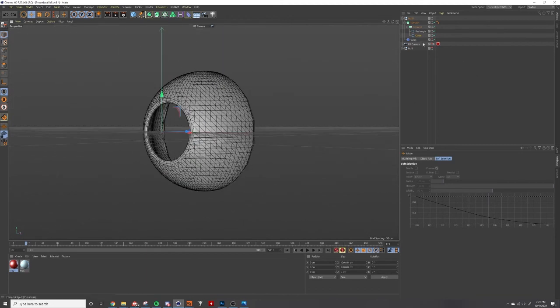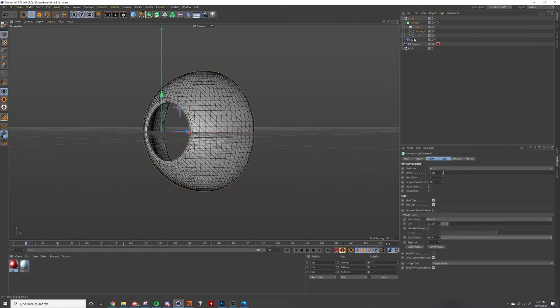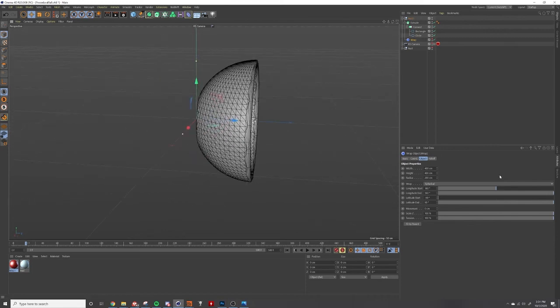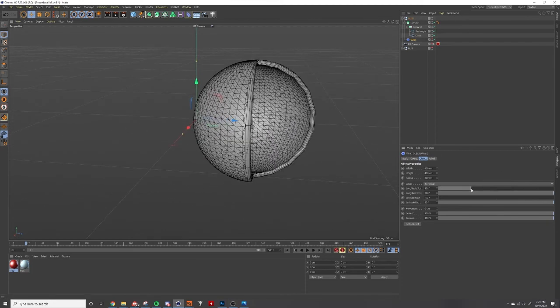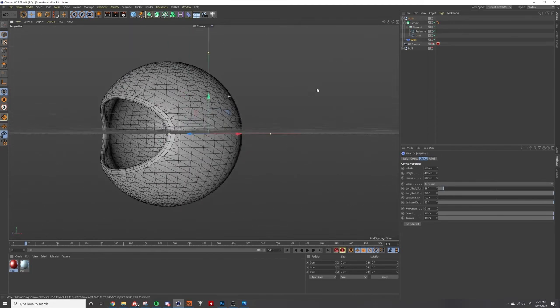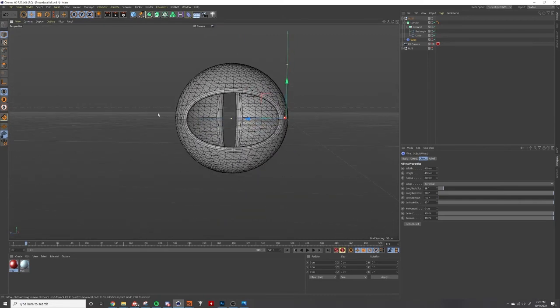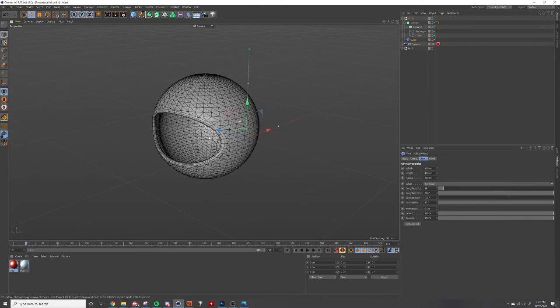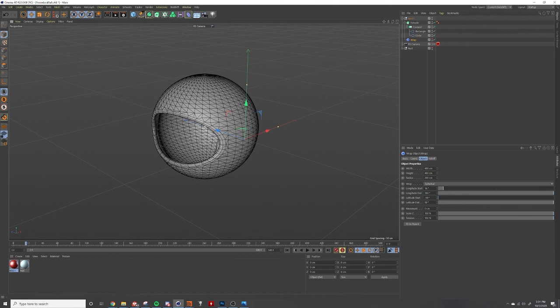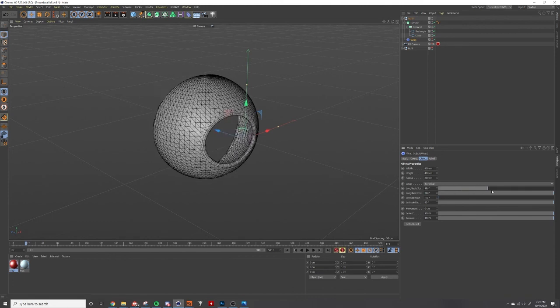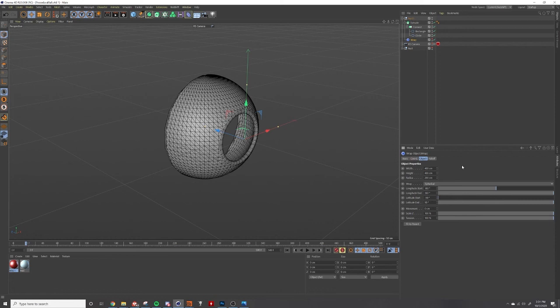But again, I said we can't use the wrap deformer to just pull it around, because that will, like I said, stretch our geometry. And look, it's even stretched our circle, which is not what we want. We want full control over this area with no exceptions. So if we go back to 180 here, so that it's nice and square,